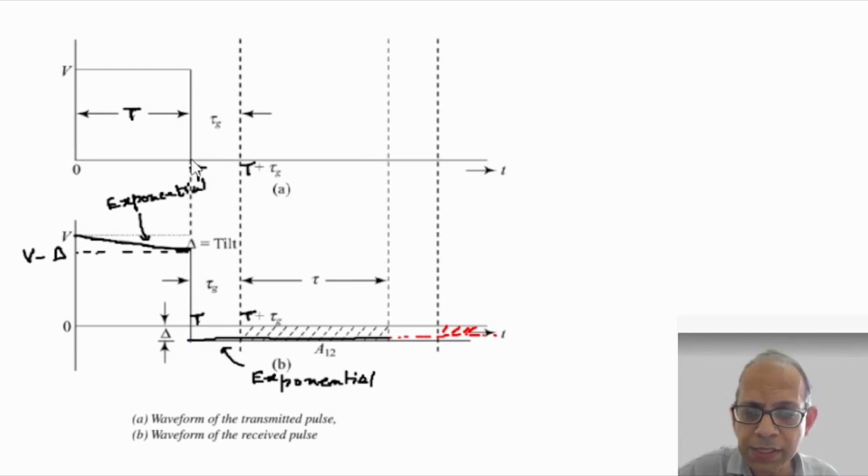And again, because there is nothing after that until the next pulse, the output starts decaying very slowly. That variation is exponential but almost constant because the time constant tau C is very large, and therefore it spreads to the next pulse duration, and not only to the next pulse duration, but even to later pulse durations because of the very high time constant.